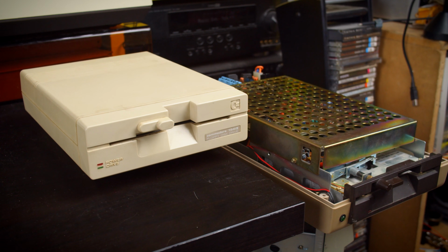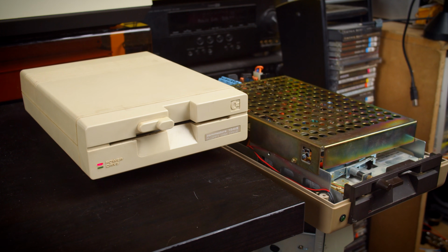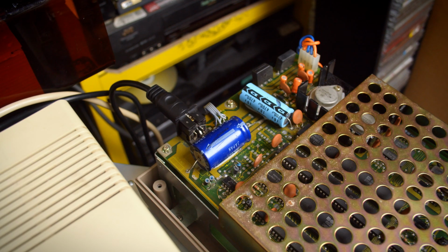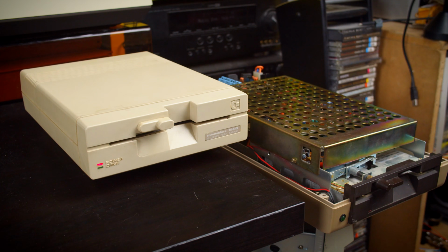Now, this will actually work because the 2 connectors are electrically connected, and as long as the main drive that I have it soldered to is turned off, the drive ID of 8 that it is hard jumpered to isn't going to matter. So I can just go ahead and use this as a really, really giant and heavy interface to connect any other 1541 drive.